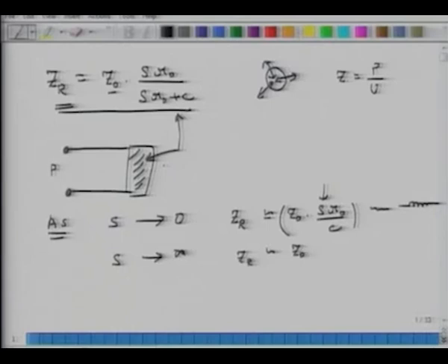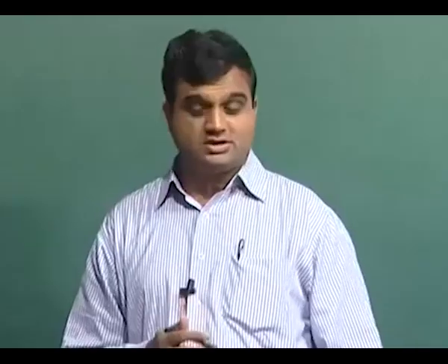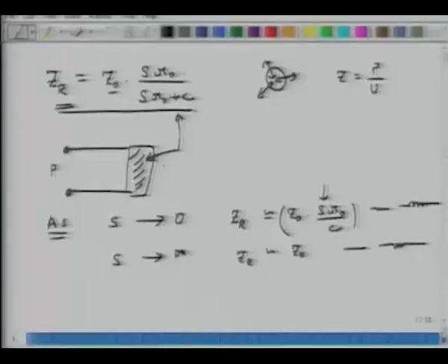So at higher frequencies, the radiation impedance looks more like a resistance. So we know that if I have to break this into electrical elements, it's composed of an inductor and a resistor. The only question is whether it's in parallel or in series. If it was in series, the form would look different. So clearly it's in parallel.